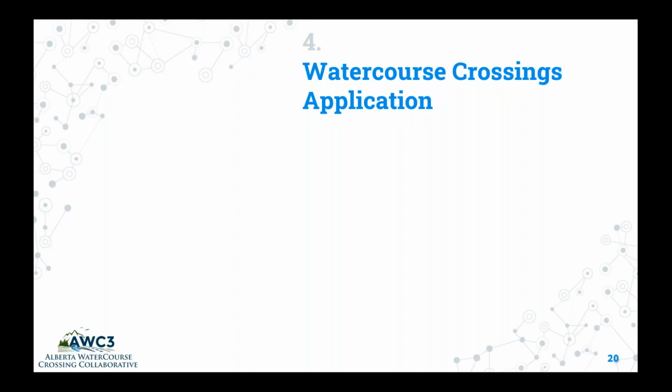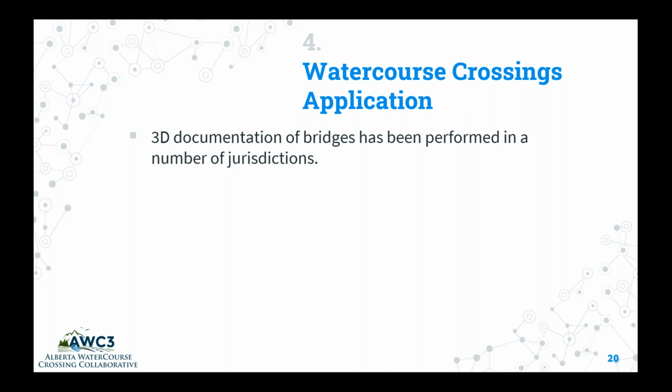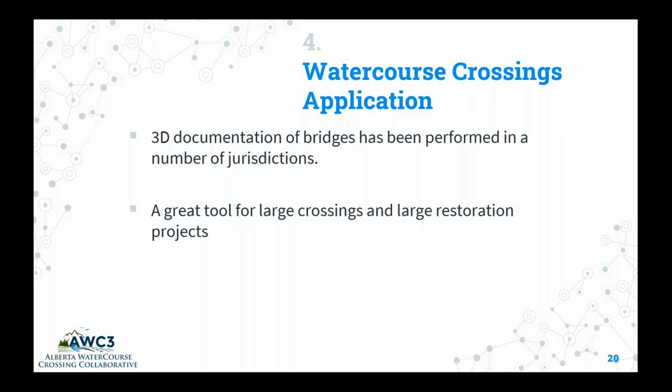Now, talking about all of the other applications, coming to the terrestrial LiDAR application in watercourse crossings. 3D documentation of bridges is fairly common. Many old historic bridges have been scanned for historical documentation. It's a great tool for large crossings and for large restoration projects. It has a limitation though on small projects where the crossing has been hindered by vegetation.